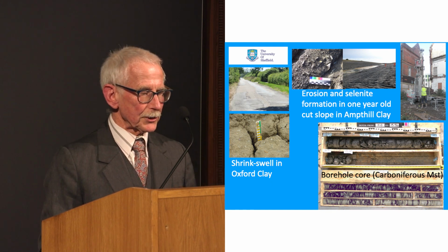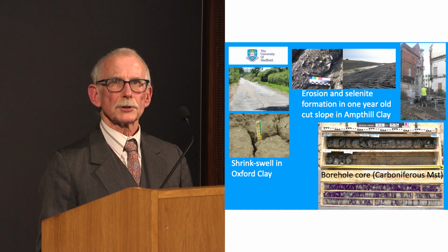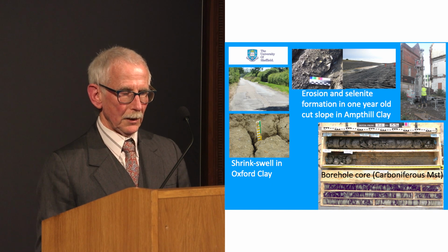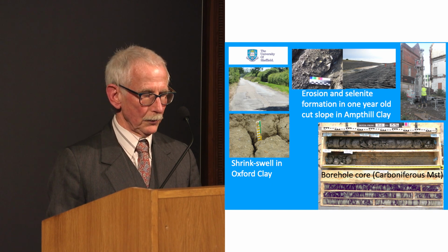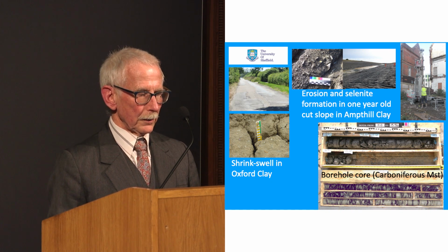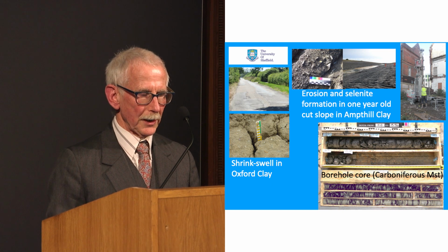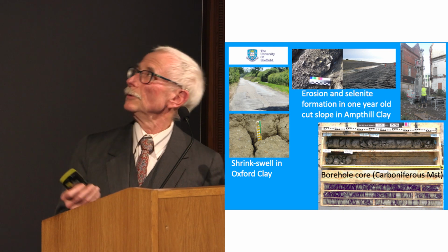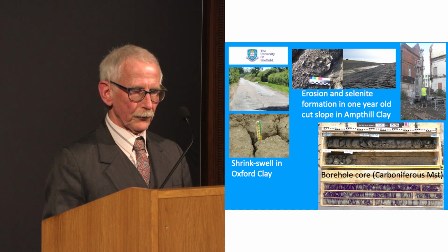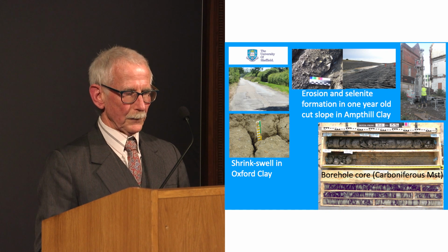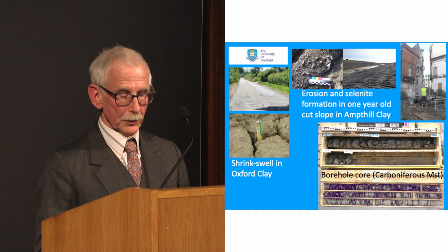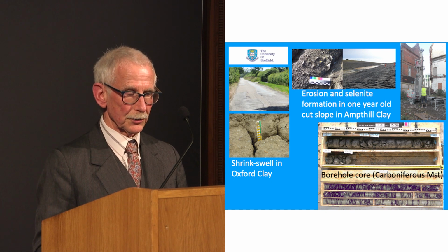I already mentioned that thin seams of mudstone can be difficult to spot in borehole cores, but it can also be difficult to investigate mud rocks. Boreholes may not recover intact core. Ironstone in the mudstone has caused the material to degrade in the upper box that you see here. And there's a loss of core, so we don't actually know what sort of material is there. The mud rock has degraded and been lost in the drilling flush.